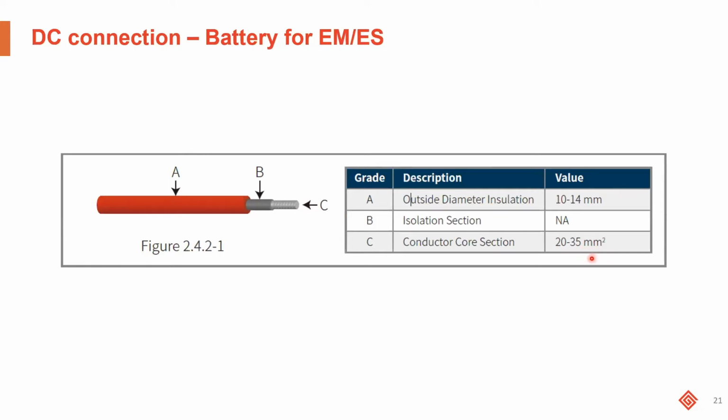Because of the low voltage, the battery is discharging high amounts of current to meet the power requirements from the loads itself. So the lower the voltage, the higher the current that's flowing throughout the system.